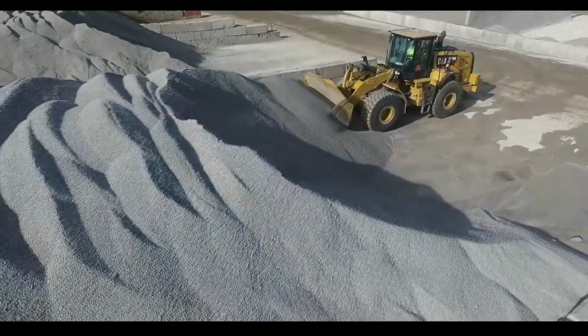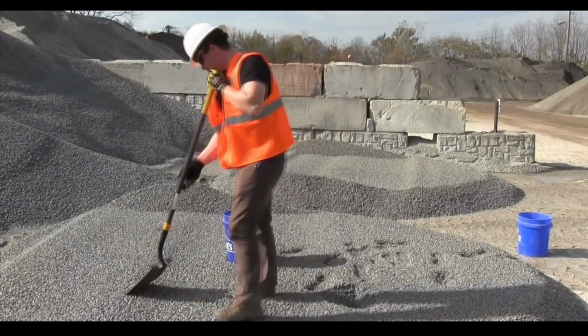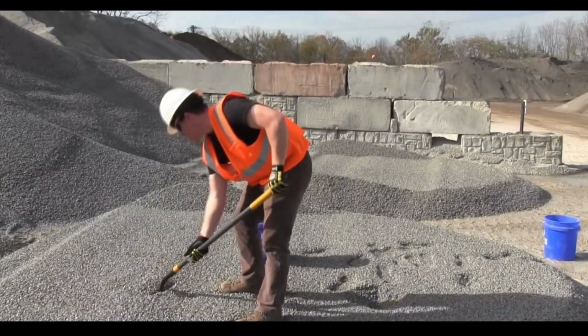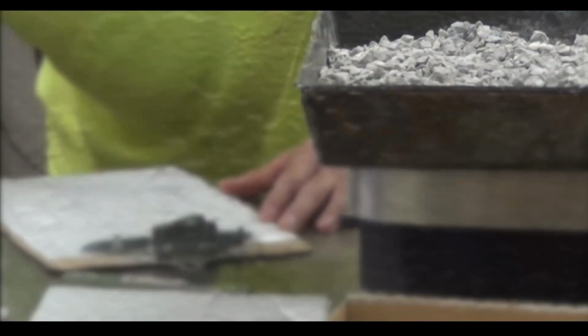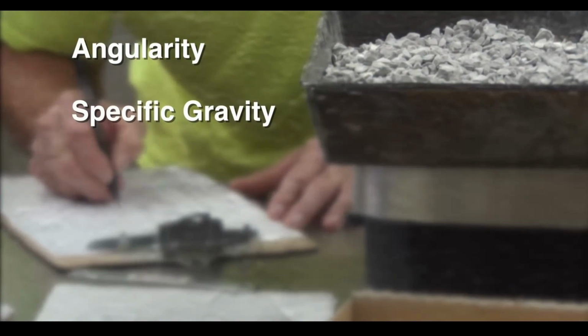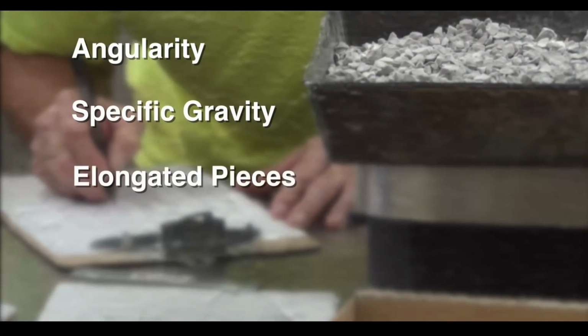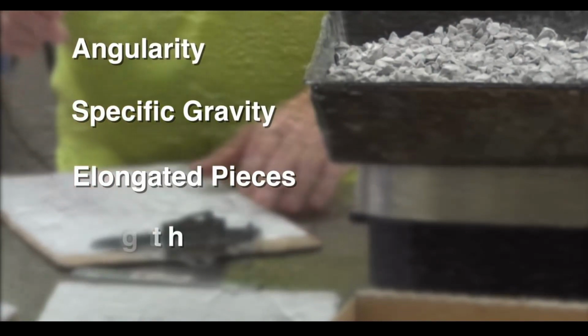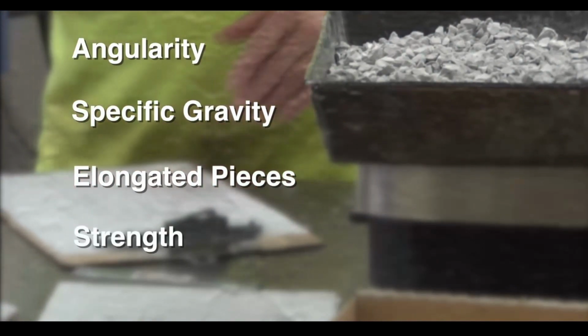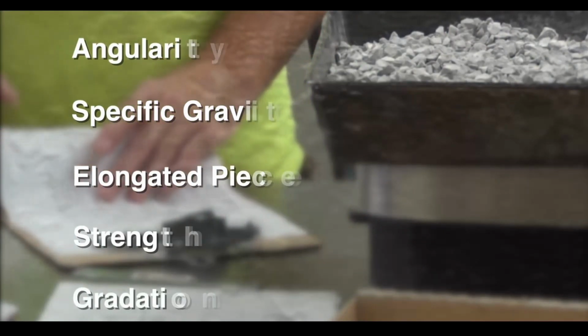Since the stockpiles at the quarry are so large, it is imperative that technicians first obtain a representative sample. Laboratory tests will be performed to determine properties such as angularity, specific gravity, which is the weight of the aggregate compared to the weight of the same volume of water, the presence of elongated pieces, and the strength of the aggregate. Perhaps the most important aggregate test is to determine gradation.